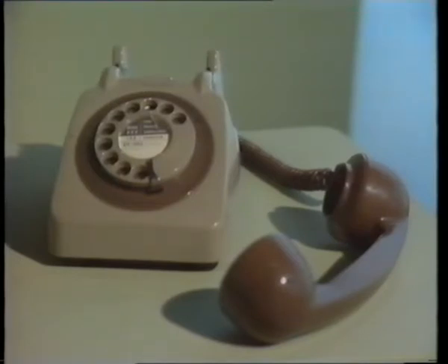We speak on the telephone regularly, with little trouble in understanding, even though here the bandwidth is limited to frequencies between about 300 hertz and 3.4 kilohertz. So the moral is, when you're deciding on the bandwidth, it's not only necessary to know which frequencies are there, you've also got to know which ones are important.